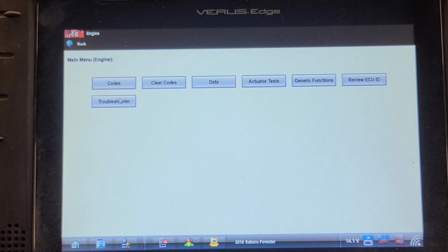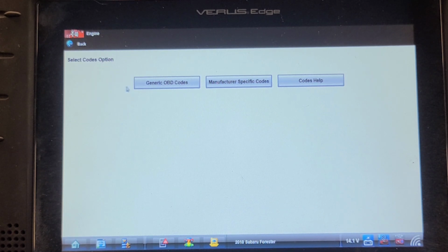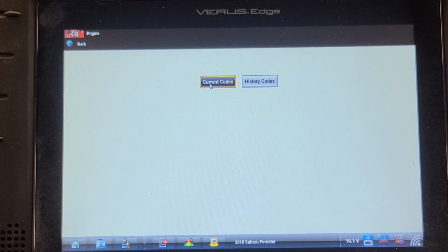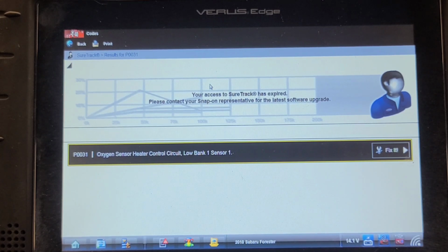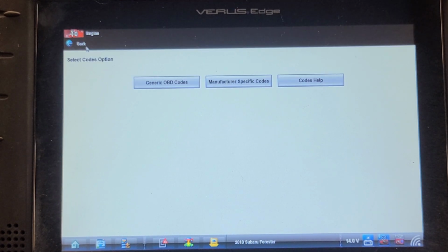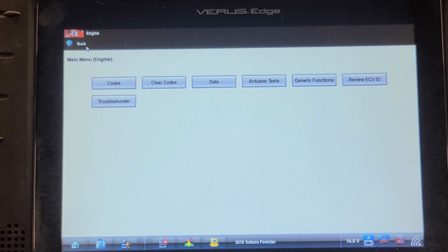Well, the light came back on immediately, and my light is not blinking. Let's see what it's got for current codes. It may not like the resistance of that light bulb. I know the sensor is definitely open, so it needs a sensor, but there could be problems with the wiring. Either that or my probe isn't making a contact in there. The car started fine, obviously. So obviously the extended crank time after the code clear is normal if you don't wait 10 seconds after cycling the key off.